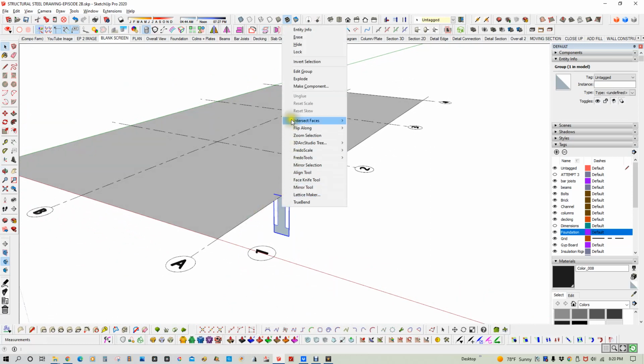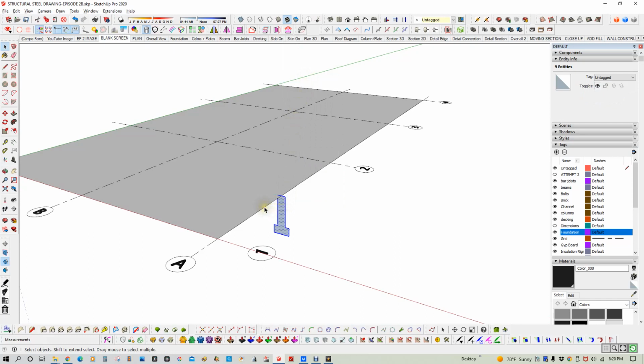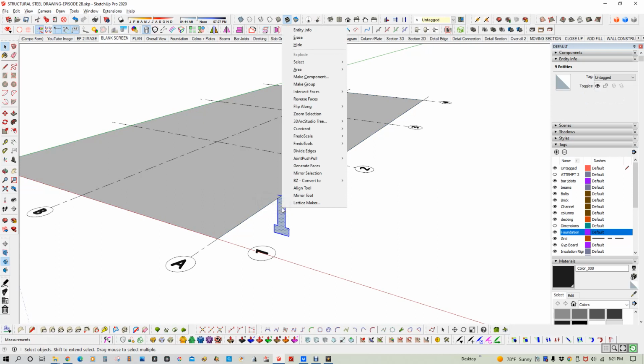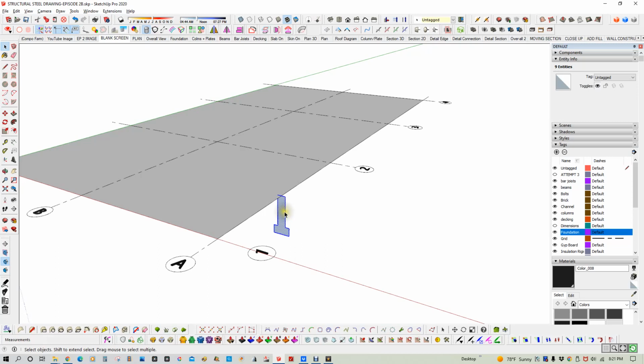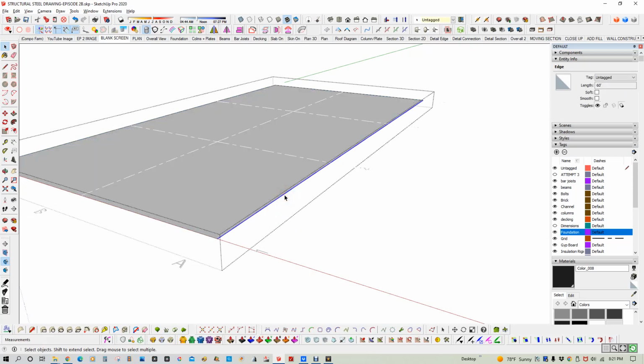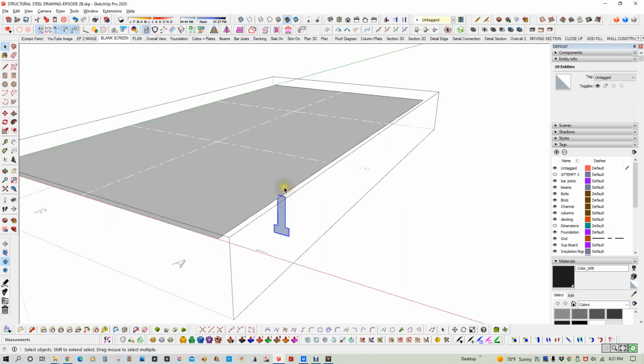So I'm going to explode this now so that I have a pieces and parts thing. Actually, what I'm going to do is this. I'm going to take the profile and Control X, which is cut. So I want to move it to this other layer. Control X. I'm going to double click on this stuff. I'm going to pick that line in particular and then do paste in place, which for me, I made a shortcut, which is D. So now I'm inside this group and I can make this profile inside the foundation. I can make this footing profile inside of that group.